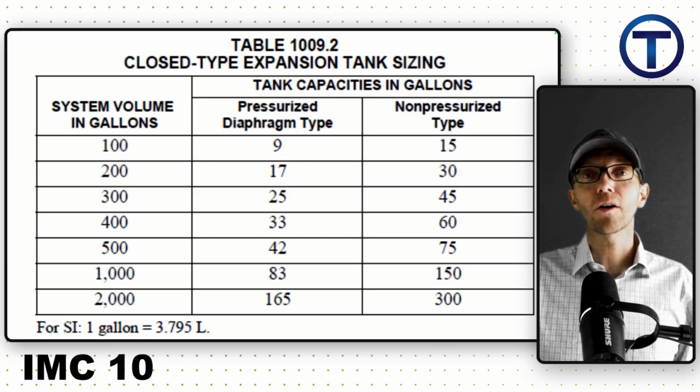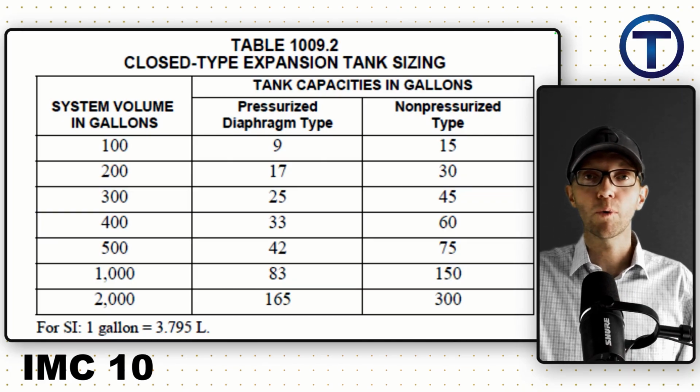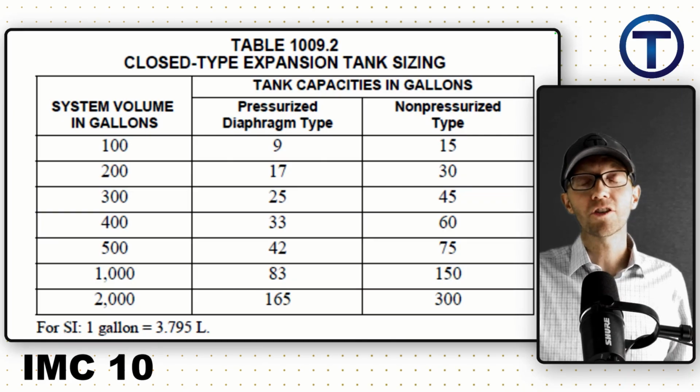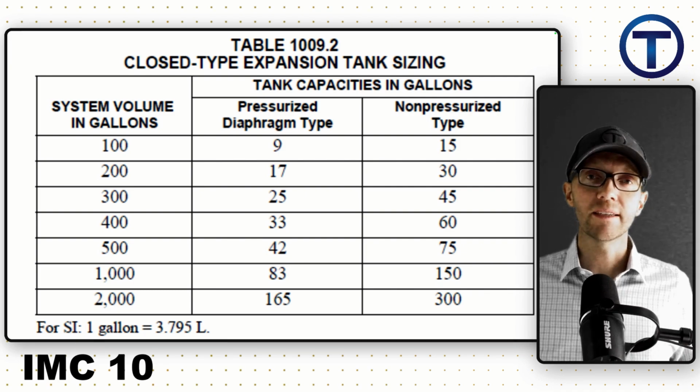Now, again, these are much larger systems than we are normally installing on potable water, but obviously those expansion tanks need to be big enough to allow for the expansion of a big system.